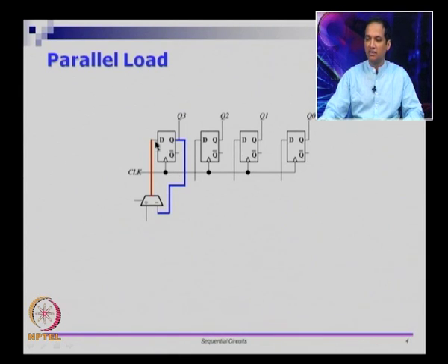Note that the D flip flop internally has some feedback path, and outside that we also have a feedback path going from the output of the flip flop to the input of the flip flop. This is a combinational feedback loop which starts from Q, goes through a mux and goes back to D. Now we wanted a load enable signal, right.